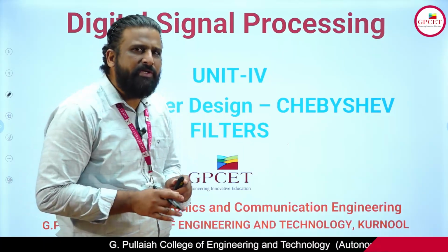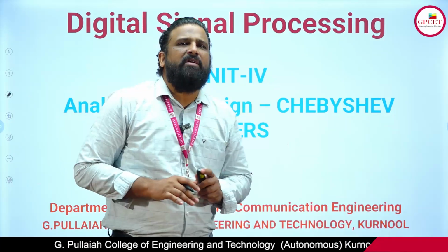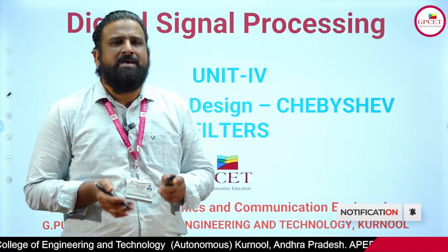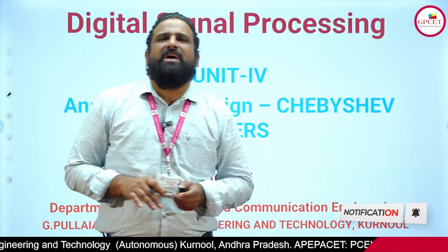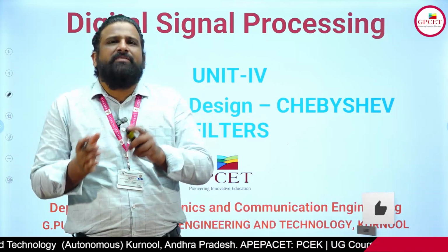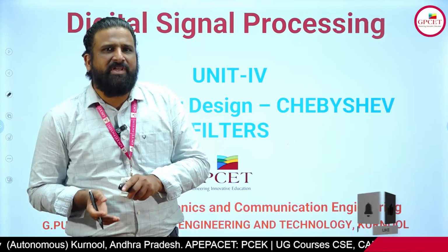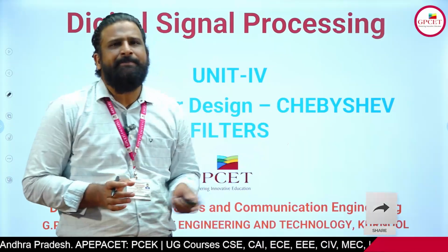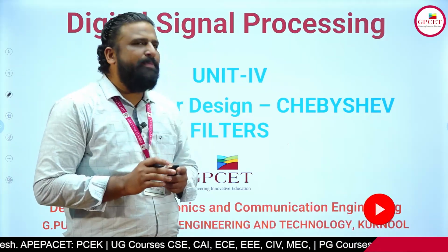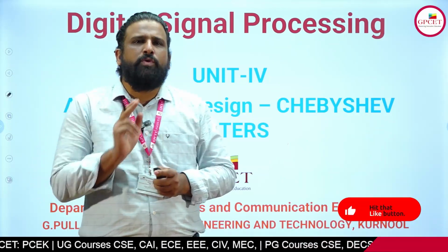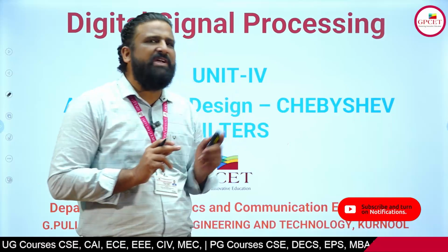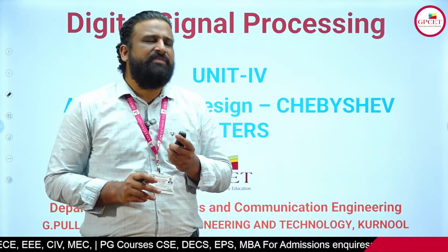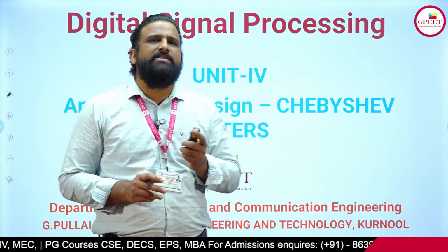First, we have to design the analog filter, that means we have to design the transfer function of the analog filter. After designing the transfer function of the analog filter, we then convert it into a digital filter. This is the step we use in the IIR filter. For that purpose we use two filters, the Butterworth filter and the Chebyshev filter.